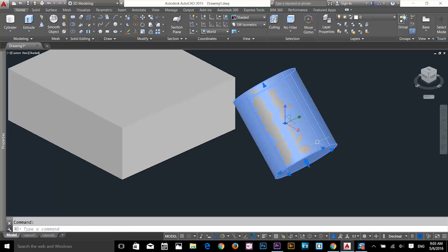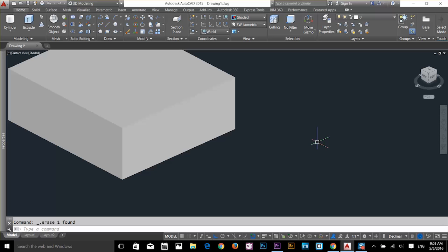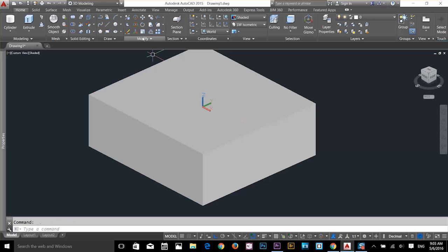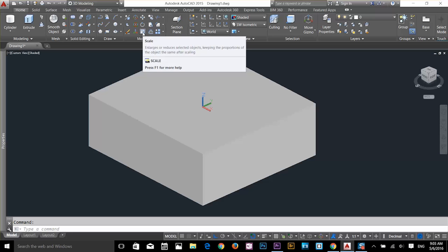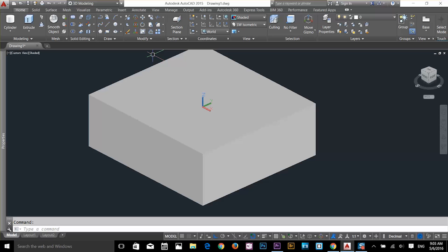So it's very useful in 3D rotate, so you can rotate objects in 3D. Here you've got your scaling, same 2D command, all that stuff. Next we got coordinates, right? These are basically the coordinates. Let's say world, top, down, top, bottom, left, so you can see your drawing from top, bottom, left and right. So these are basically 2D commands.